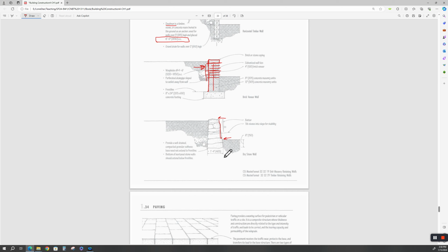Now, if all you've got is stones and you have to build one of these, you'd better use some epoxy-based mortar and try to get some reinforcing in there some way, somehow. I've seen some of these where they've had to go back in and, to save them, put structural elements on the outside and drill tiebacks back in the soil with the dead men. They had to dig down in here and do tiebacks to hold this stuff from falling apart.